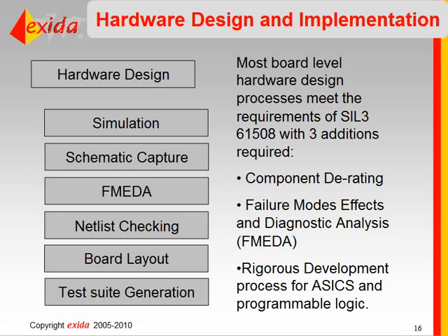So it doesn't get into too much about how you do schematic capture, whether you do simulation or not, how you do board layout, how you do some of your hardware-specific testing. So most processes out there should be compliant or pretty close to compliant due to the fact that there's not a lot of requirements there. But the 3 areas that sometimes are issues are component derating, failure modes, effects, and diagnostic analysis, and the rigorous development process for ASICs and programmable logic.